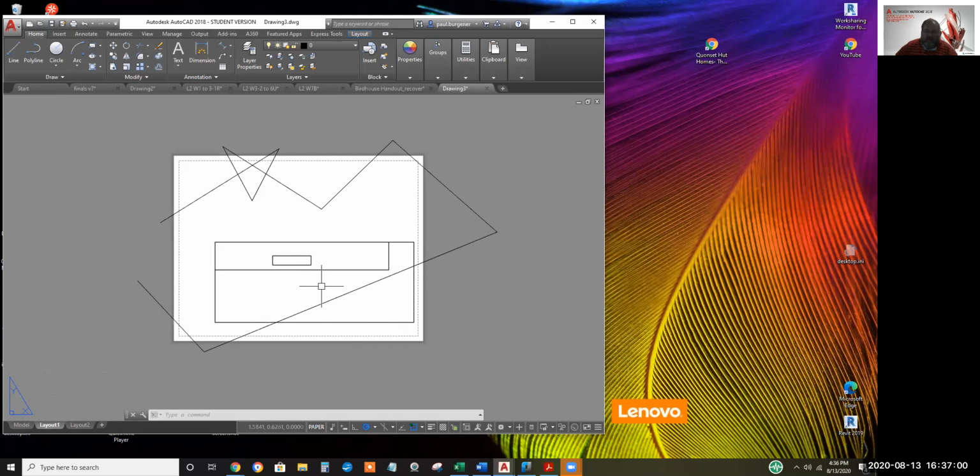Once you stick your hands through the glass and push and pull and rotate and edit and pan and zoom to get your model space stuff to appear, in most cases, I just noticed an exception today, the viewport turns into a bold line. So you got three visuals of whether your hands are inside the glass or you're standing on the sidewalk and your hands are outside of the glass.